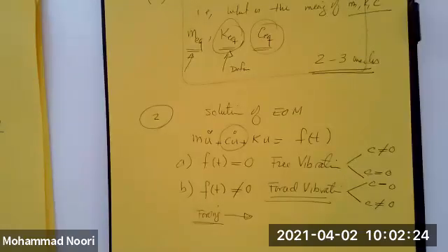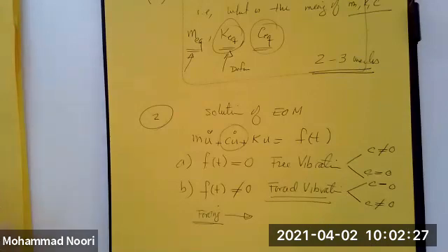In other words, you have a vibratory motion and you say, okay, I put the inertial force in the opposite direction, what happens? The system is going to be in equilibrium now, static equilibrium. So that's called the D'Alembert principle. What D'Alembert did was exactly that. And so you can simply write sum of all forces, including the inertial force, is equal to zero, except that the inertial force is acting in the opposite direction. You will see how we are going to apply this.